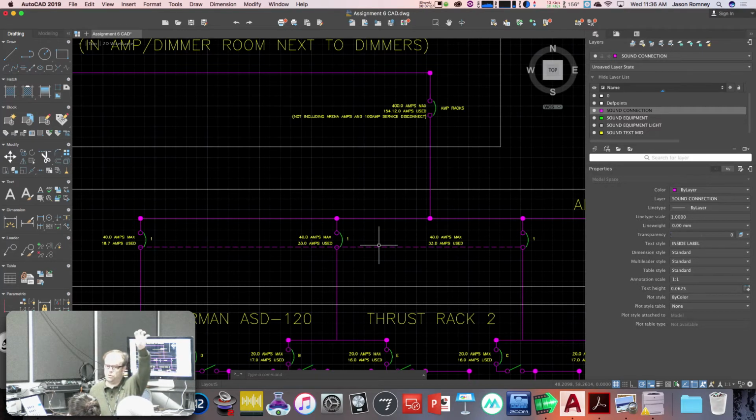If that master 400 amp breaker decides to trip, it takes out not only your show, but it takes out the show in the Catawba as well. Okay, so if you're the one that does that, it's not just you that suffers. The show down the hall is going to be very angry with you as well.